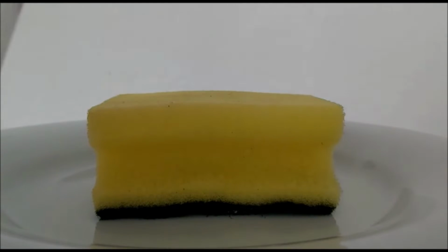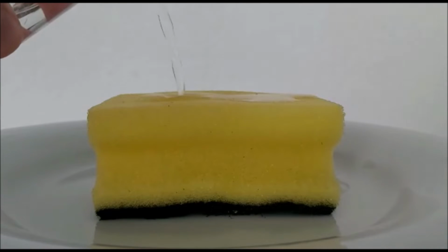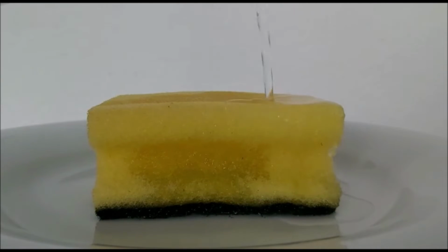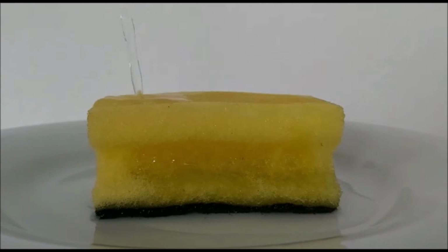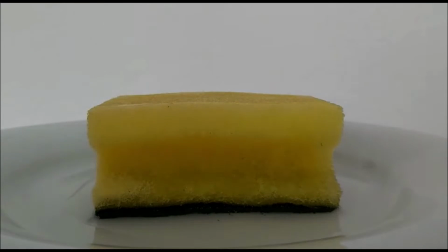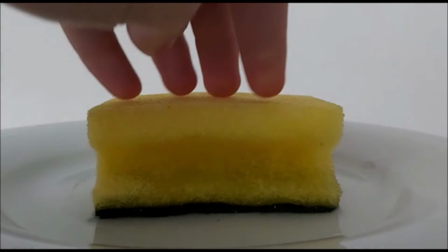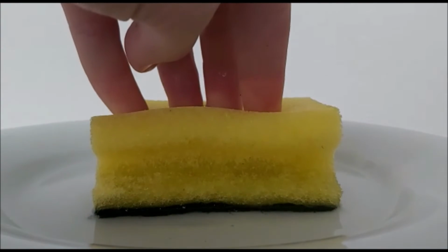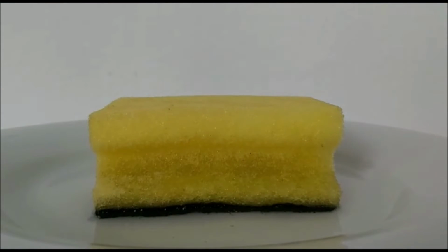But if you build a wall with a high amount of voids, such as mineral wool, you have to protect it from water. Because if water enters the voids, the air is pressed out, and water is the new major constituent. Water has a thermal conductivity of 0.6 watts per meter Kelvin. Just as a reminder, air had 0.022.